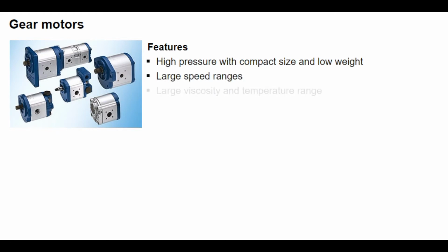Gear motor power depends directly on flow and pressure difference in the motor, since the displacement cannot be varied. The design determines the volume of the displacement chambers, and this space between the gear teeth cannot be changed. Gear motors are compact and lightweight. They are among the high-speed engines and give off both a large starting torque and a high continuous power. For motors which are intended for only one direction of rotation, high and low pressure side are determined. They can no longer be reversed.